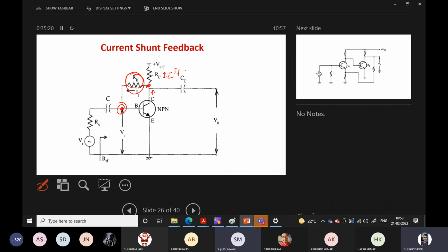Tell me, is this resistor connected in series or shunt? Series, R1 and R2. But in series, the current does not divide, it is the same. In shunt, current is divided. If from a common node two resistors or multiple branches appear, that is connected in shunt. That is the simple thing.